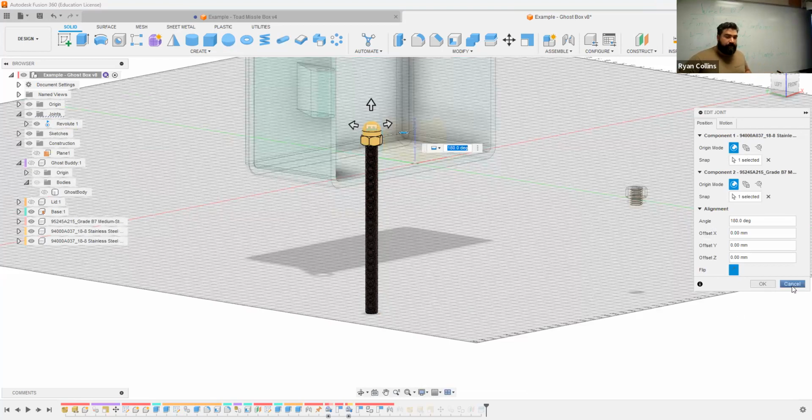Can you delete the split body? I can, but I want the split body to exist. Like, you want the top part to exist on the split body? No. The question being, can I just delete the split body action and do something else? Yes, but I'm trying to use the split body to shrink that threaded rod to the correct size. So really the more effective option would have been to go back and pull my history slider back, do it then. So that's your options. You can either delete these and repeat all this, or exactly that.